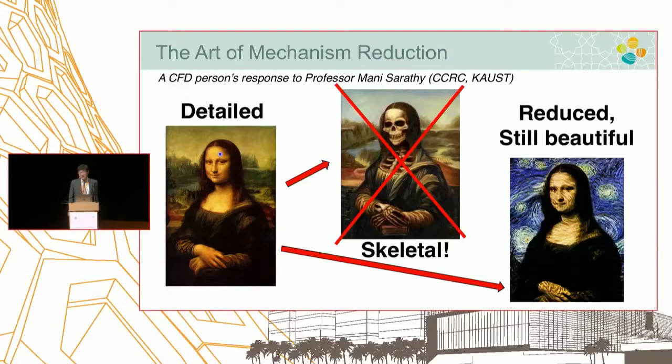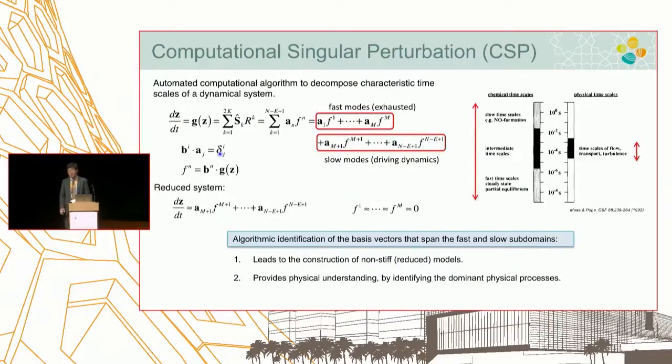In my opinion, there's a lot of common misconception about these stiffness issues. And people try to throw everything in and just hope to see. Why do you do that? I mean, why do you need all this fast time scale if you don't need it? So do it carefully beforehand and remove them. Once you remove them, I don't need an implicit time integrator. So that's my vision of high fidelity DNS.